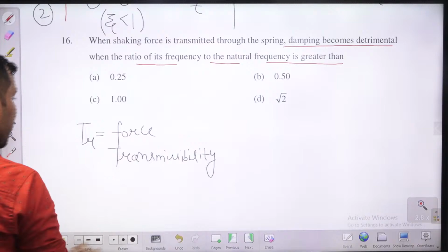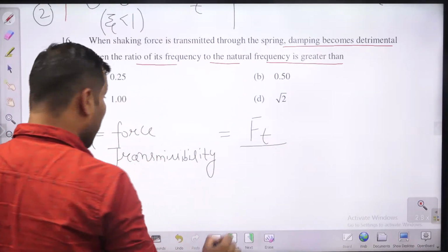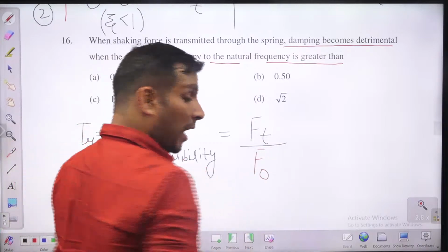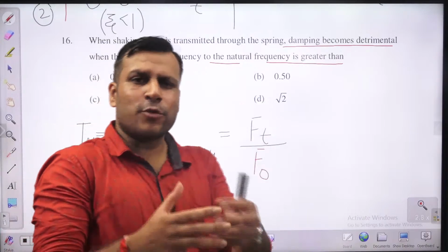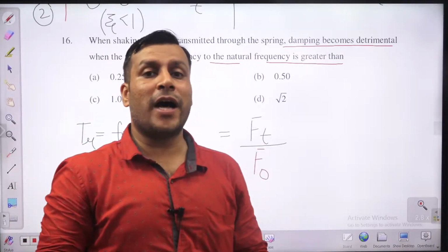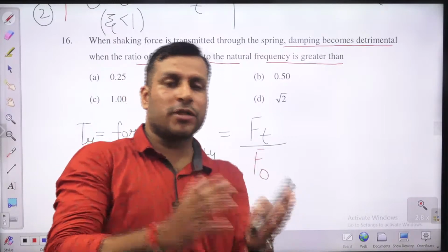Okay. This is nothing but the ratio of the force transmitted to the unbalanced force applied. Suppose we attach some kind of isolation just to restrict the force transmitted to the foundation.